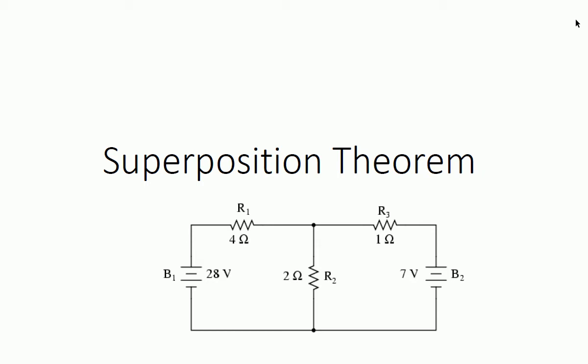It could be the power supply you find in a car. You've got a running engine, and your own little power station, which is the alternator. The alternator produces, I just checked it outside yesterday actually, 14.6 volts. Mine should produce about 13.8 or 14.1, that's a nominal value. Then you've got your battery, which should stand at about 12 volts, maybe 12.5 volts, depending whether it's fully charged or not. In both the alternator and the battery, you've got a little bit of internal resistance depending on the current that you pull out of it.